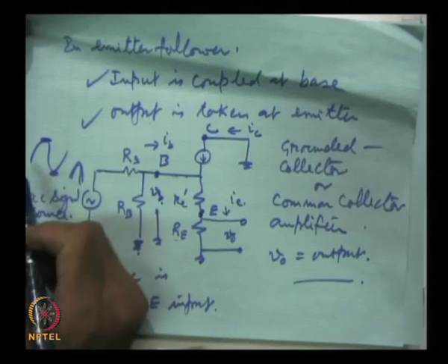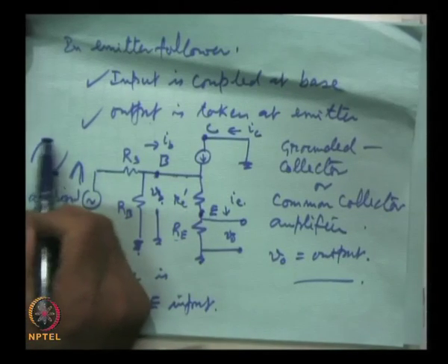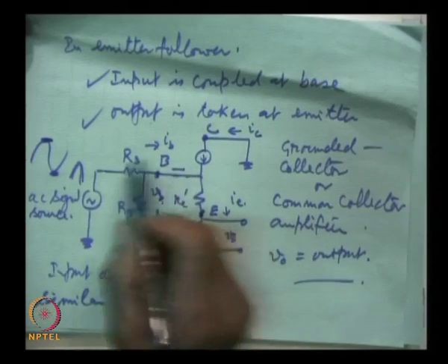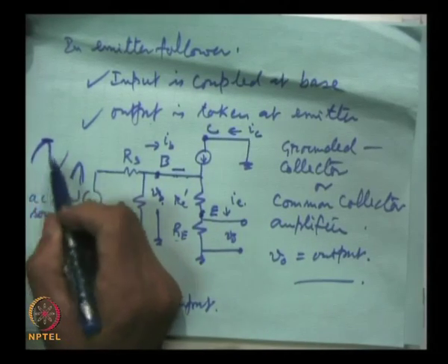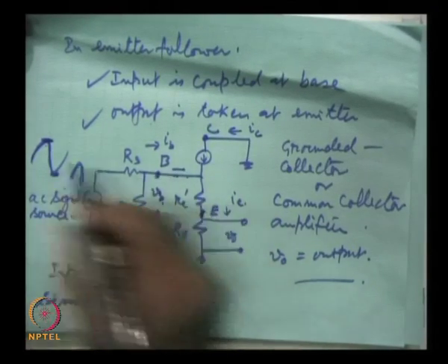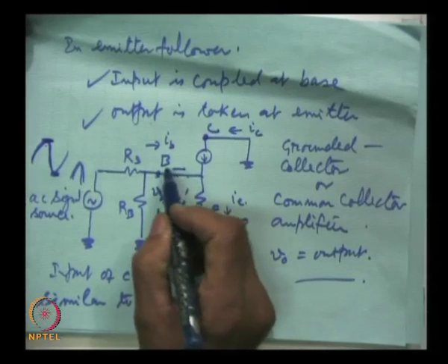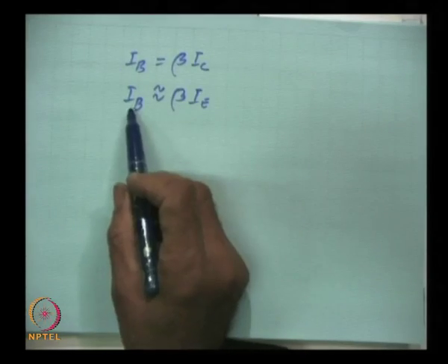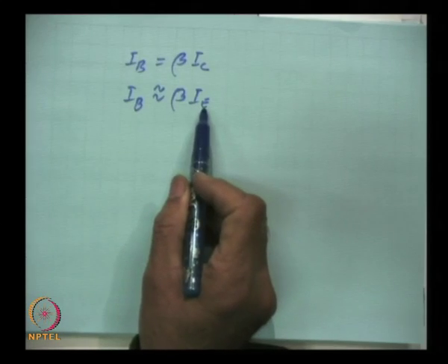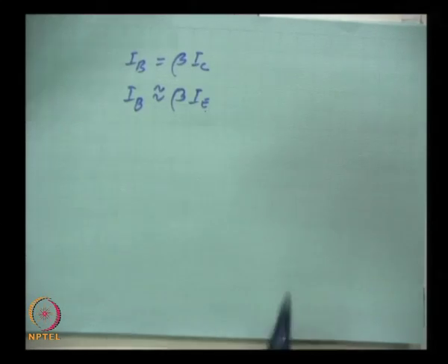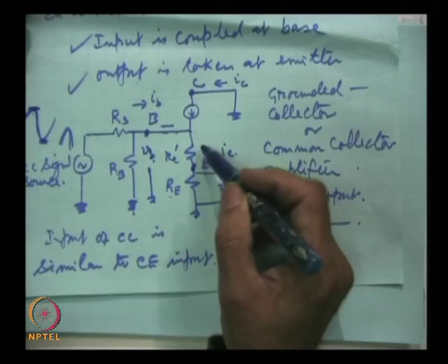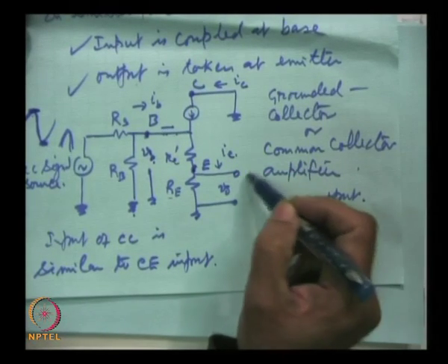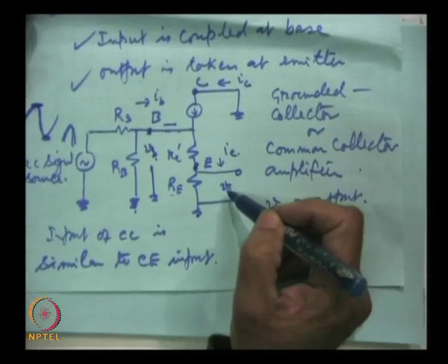So, now we are talking about the point when the base current is highest, then this positive half of the signal at the peak value will give a large value of I_B, and since beta is constant, I_E will also increase, and then the drop across this, that is the AC voltage varying across this, will also be high.